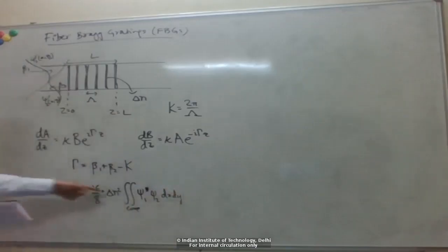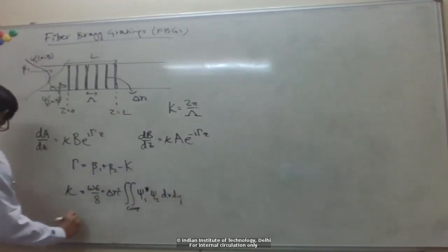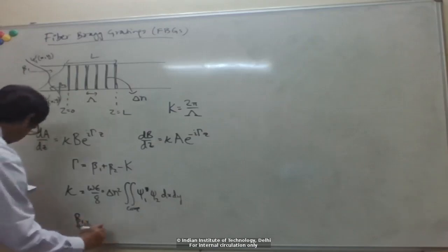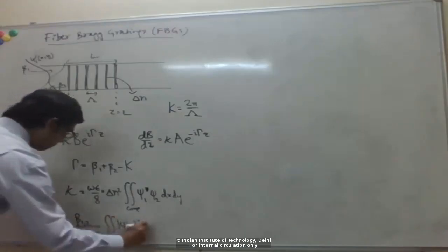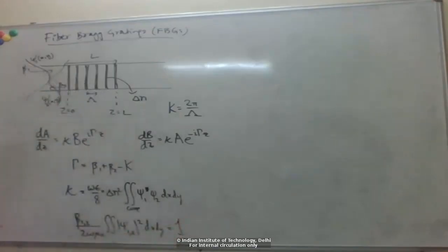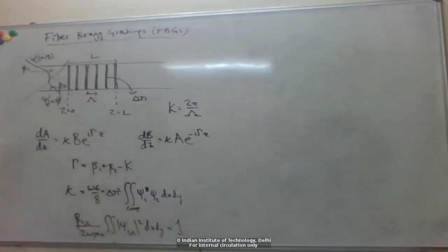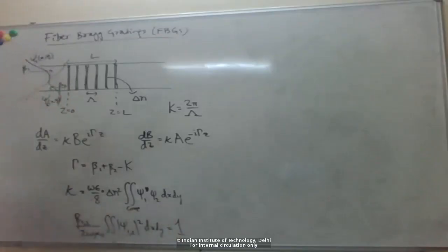We wrote this assuming the modes are normalized such that this integral is 1. That means they carry unit power, because this is the expression for the power carried by the mode.